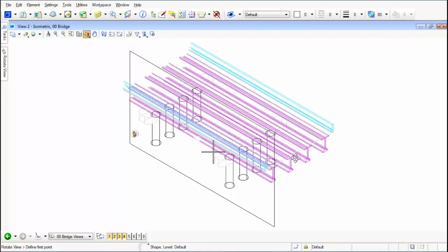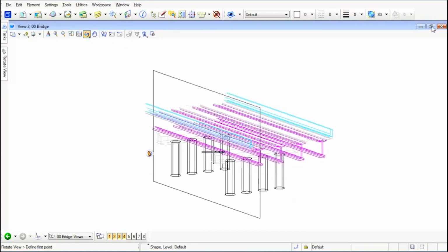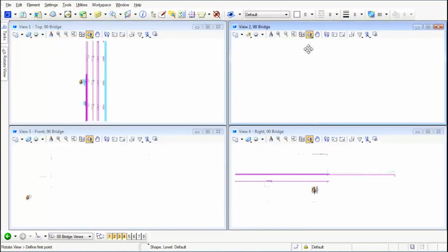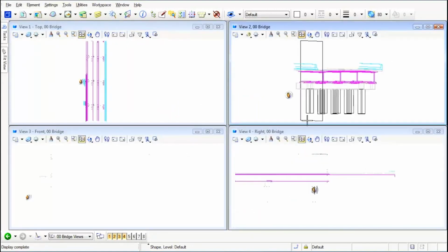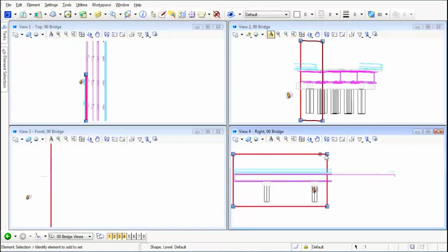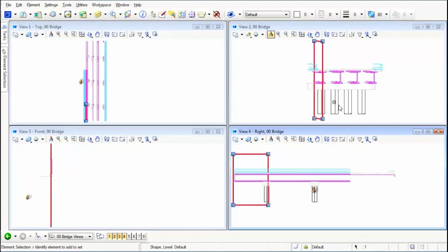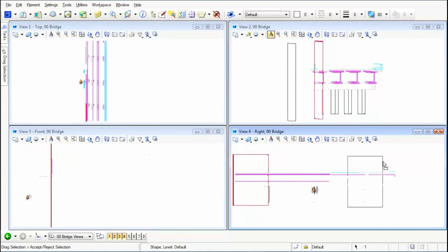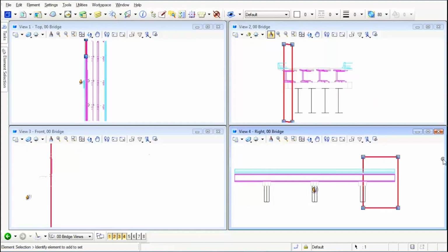Now the beauty of this is that any given time that you want, you can tell MicroStation that you want to adjust this. So I'm going to come back up here to my task, select my arrow, and then of course I can select this border. Now with a single click of my handle, I can get a different set of results. Notice how it's more narrow, as well as the fact that I can also move this around just by holding down the left mouse button and selecting what portion I really want to see.